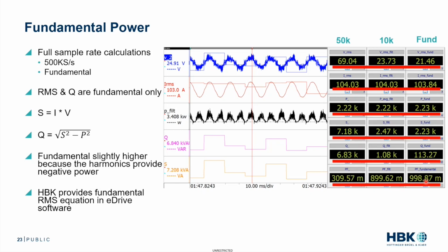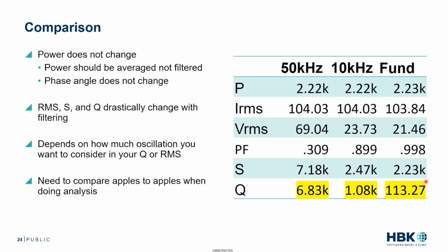That's the question. And I lay it out on a nice little table, and the questions are valid when people say, why is my measurement on one instrument different from another? Why is my MATLAB calculation different than my instrument? Why is my scope different than my power analyzer? By really drastic sums. Well, you have to ask yourself, what are you filtering at? Why is my model different? Well, what filter does your model have in it? How ideal is it?